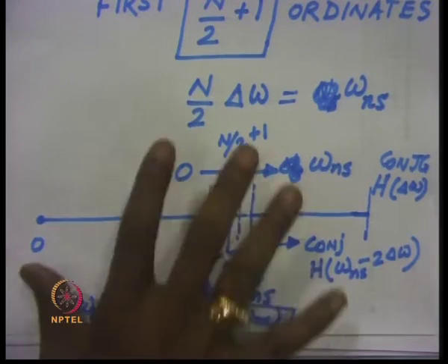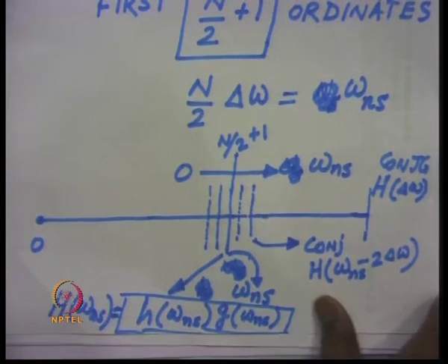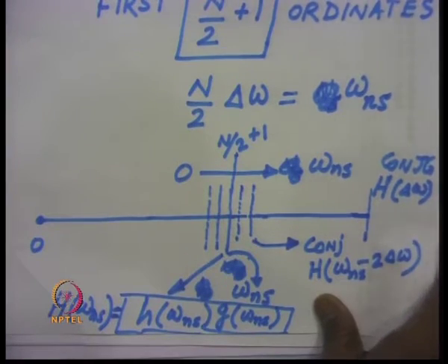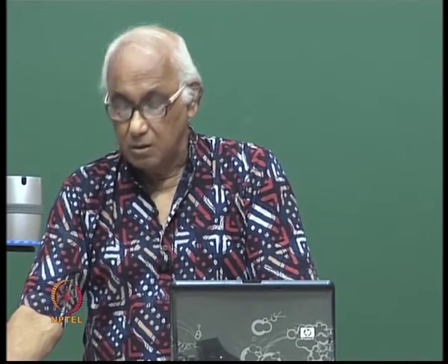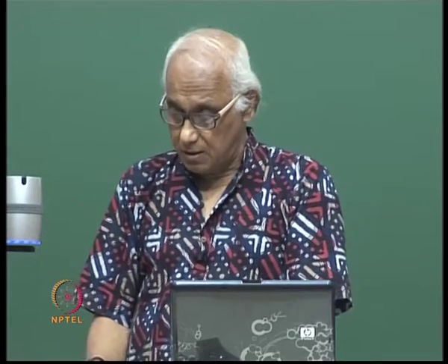Now, once we give these 32 complex numbers, that means on this side we have complex conjugate numbers, then the IFFT would give us the response of the single degree of freedom system to the specified ground excitation of xg(t). xg(t) is the ground motion.